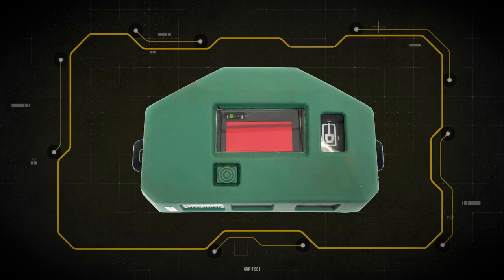by the SIM. The LD LED will briefly flash green, then red. Then it will flash green twice per second, indicating that it is ready to receive the configuration code. Once it receives the configuration code, the green LED will stop flashing. It will illuminate green for 3 seconds to indicate a successful connection. If the LED illuminates red, try again by pressing the button on the front of the LD.